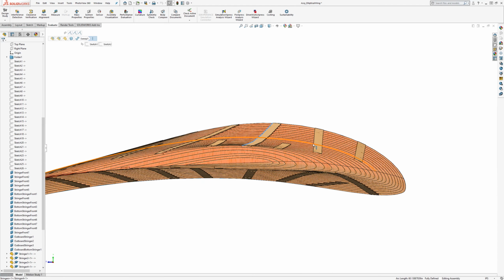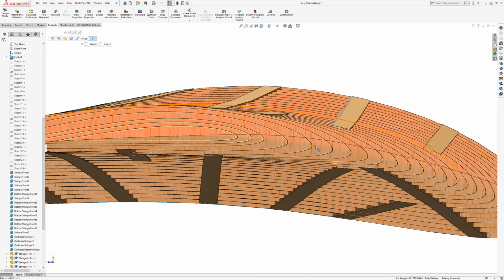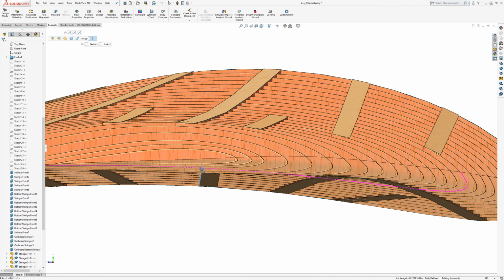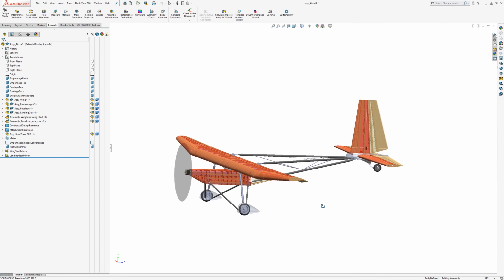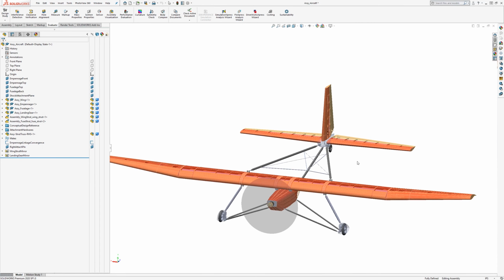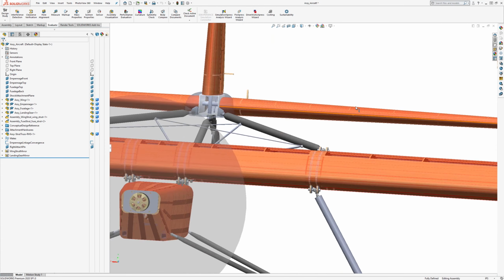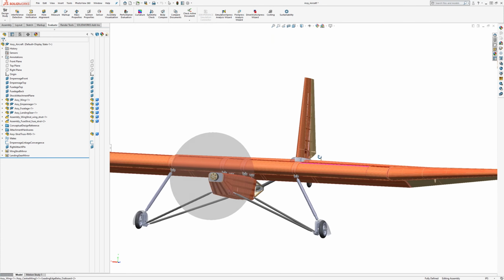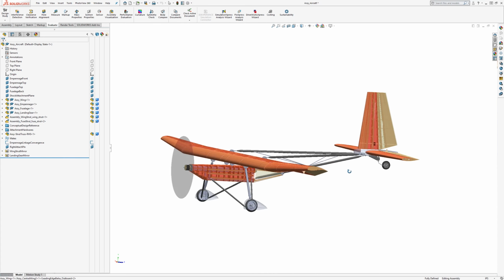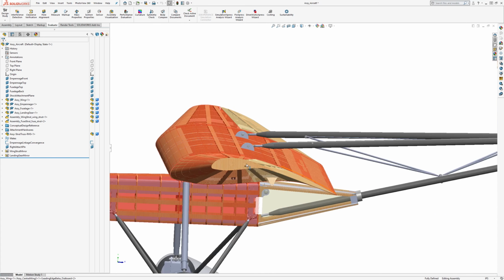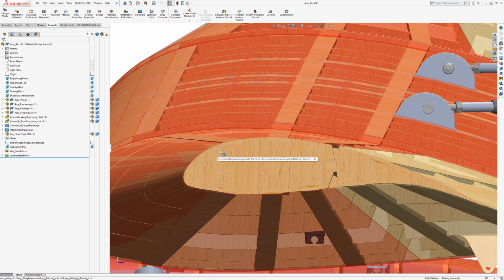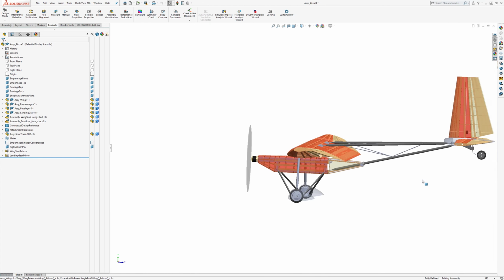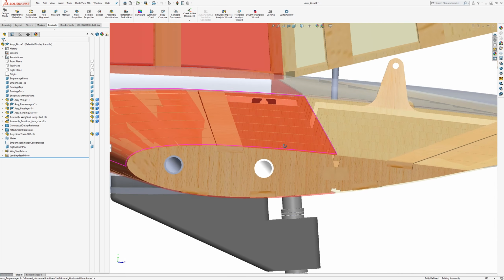Now, that's in contrast to, so let's look at a straight tapered wing. If we take a look at straight tapered wings, they do clearly have curvature along the direction of the airflow, but regardless of their taper or washout, we can find along the OML of the surface straight lines that don't curve, for instance if we look down the stringers.